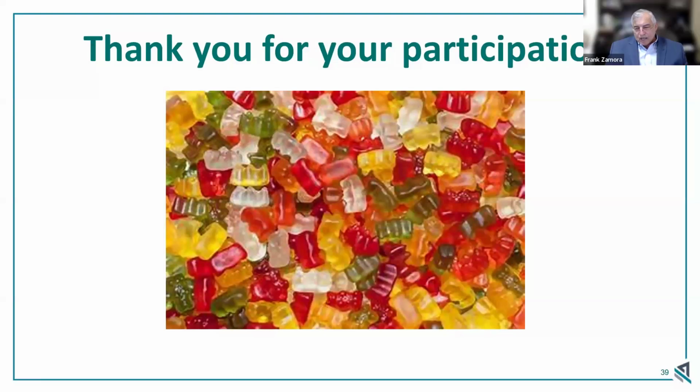So, I mean, that's a good question. I think it's important to make sure that your fluids are definitely compatible. You kind of have to look at it from a holistic perspective, from cradle to grave until the well is put on production. But what you're hoping is that your bottom hole is supercharged. You just got through with the frac, so your formation is supercharged. So you're hoping that the bottom hole pressure is going to keep that invasion to a bare minimum. And hopefully it's not going the opposite direction whenever you're drilling out, where your hydrostatic head is exceeding your bottom hole pressure and you're actually leaking fluid back into the fracture itself. If that's the case, then yeah, you're absolutely going to cause an additional problem if you don't have the right polyacrylamide.